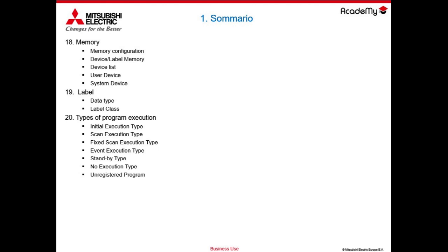Next, we will talk about labels, the variables defined by the user in the PLC programming phase, each with a unique name. When we talk about labels, we will differentiate the local labels, those locally defined in a programming container and consequently exclusively usable by it, and the global labels, globally defined in the project at a predisposed point to contain and define the global variables.